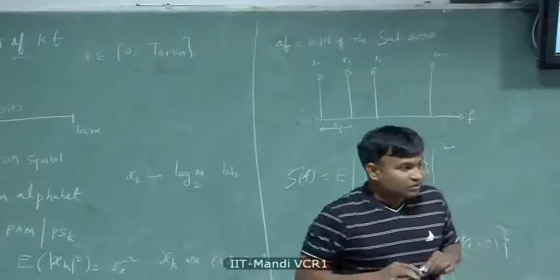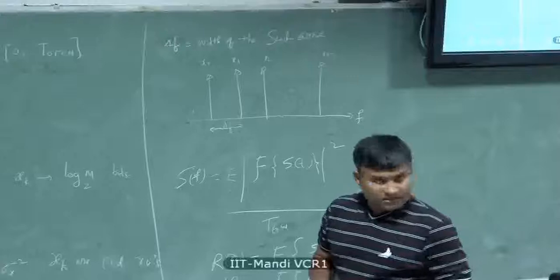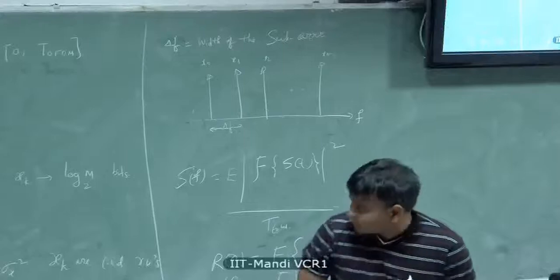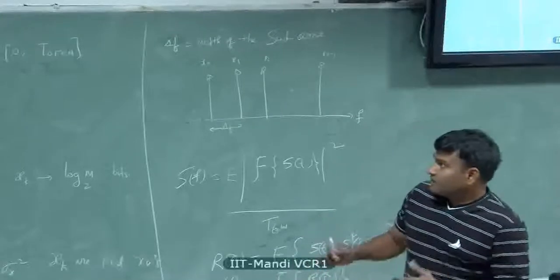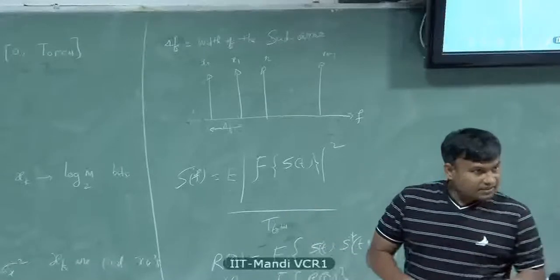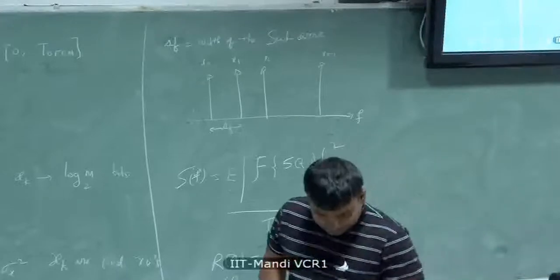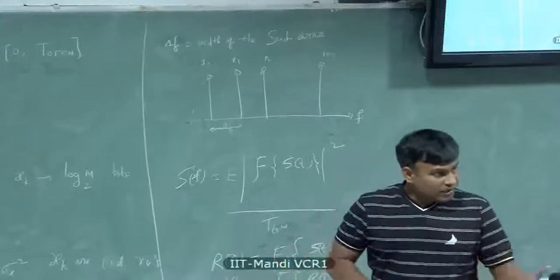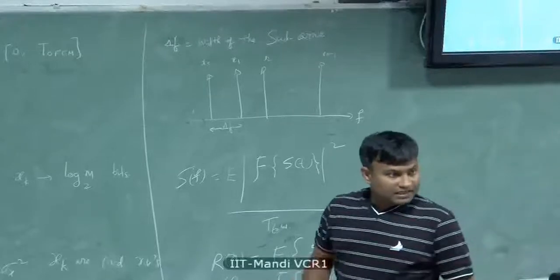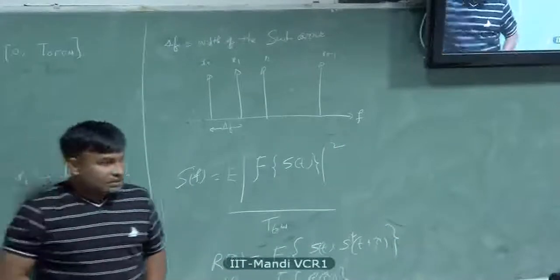So the entire discussion will limit itself to low pass equivalent signals, which I call sometimes baseband signals. So you don't get confused when I say baseband or low pass. What we'll now do is describe an OFDM signal, what it looks like. Now we'll receive this. Of course, I will not impose any propagation channel in between. That unnecessarily complicates the discussion at this point. However, we'll introduce additive white Gaussian noise, which is always present in the receiver, which we cannot ignore, and develop a receiver which allows us to demodulate the information carrying symbols x of t.